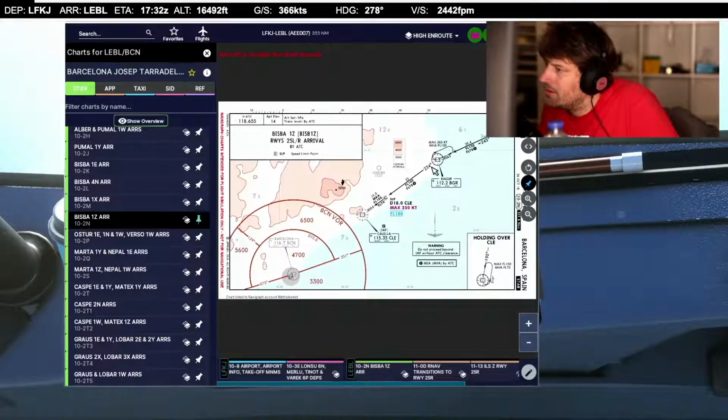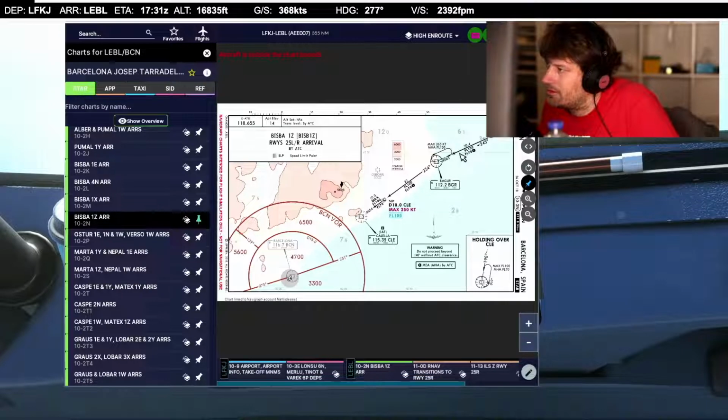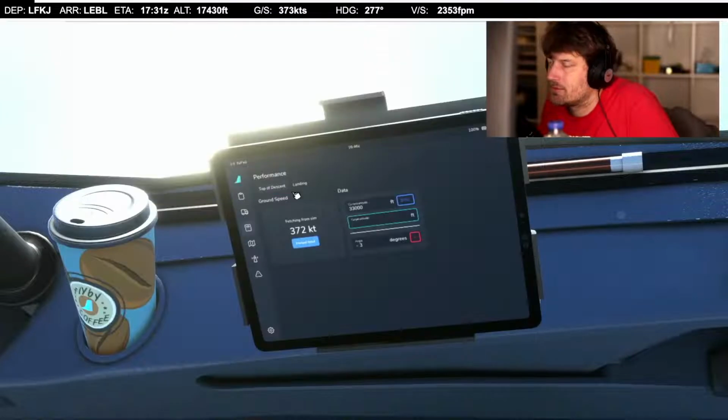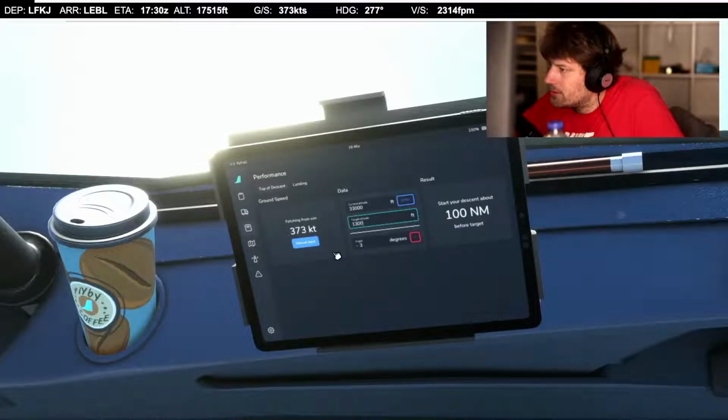It's the lowest. Yeah, this route should go flight level 130. So let's assume we want to go to flight level 130 before descending to flight level 100 until Charlie Lima Echo. So it's 20,000 feet to lose, so 60 nautical miles.